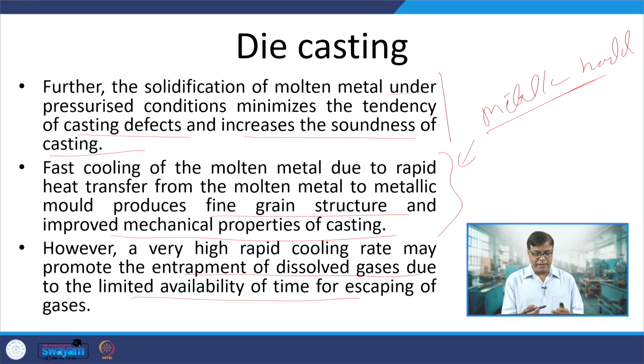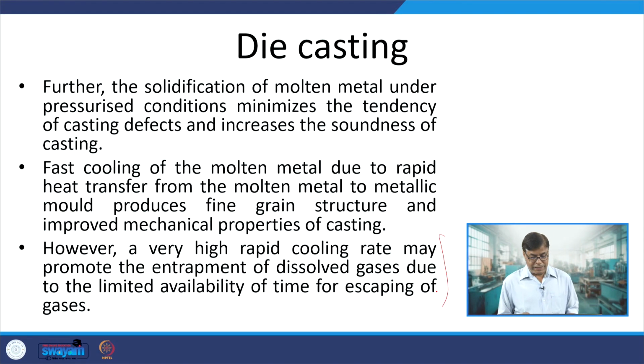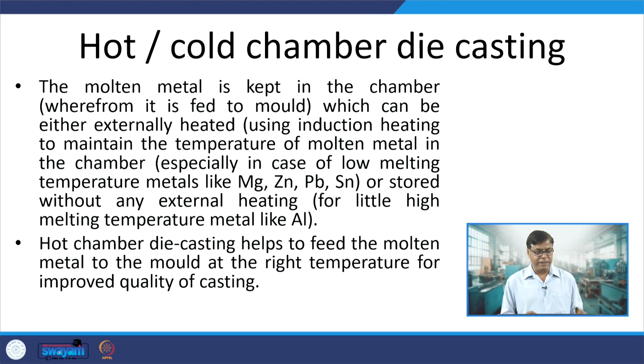So, on one side, the faster cooling rate is good for producing a fine-grained structure and better mechanical properties, but it may increase the tendency of entrapment of gases and inclusions. In die casting, the molten metal can be fed in two ways.